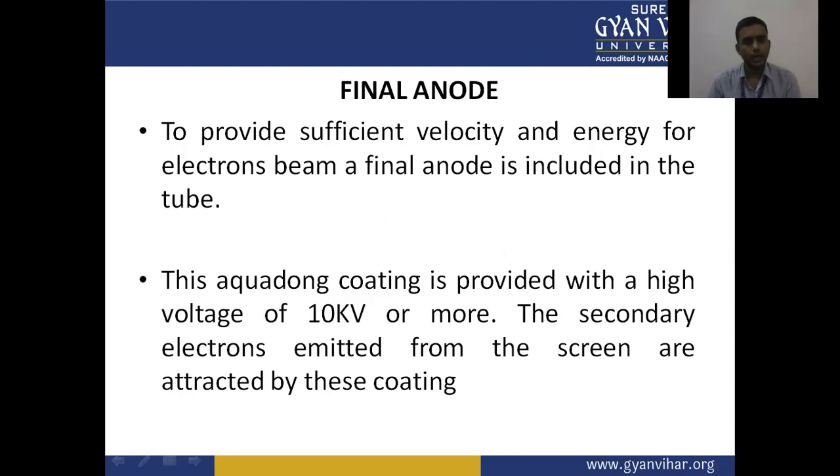This aquadag coating is provided with a high voltage of 10 kilovolts or more. The secondary electrons emitted from the screen are attracted by this coating.